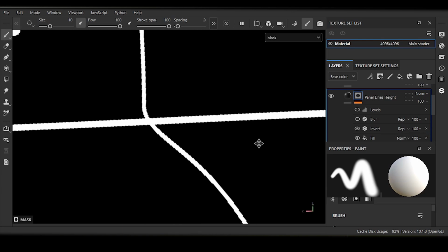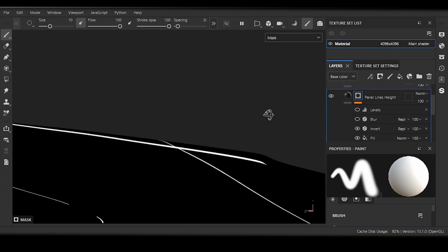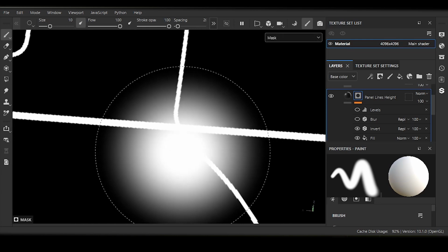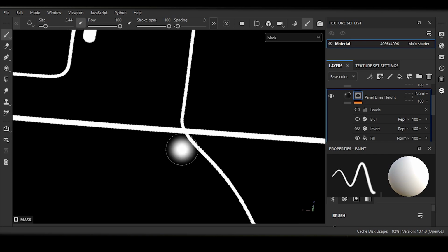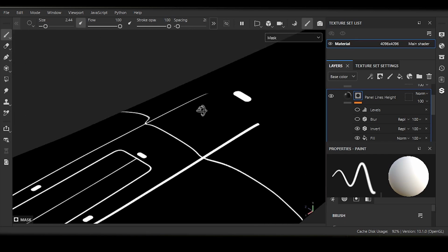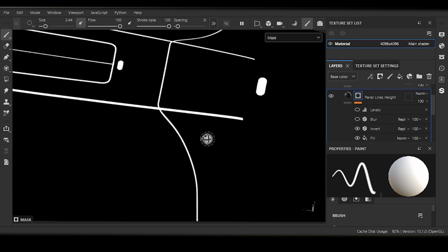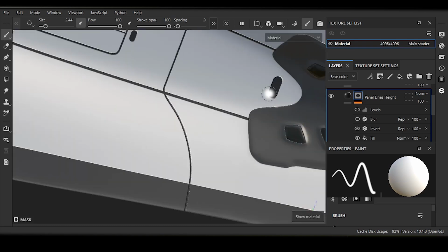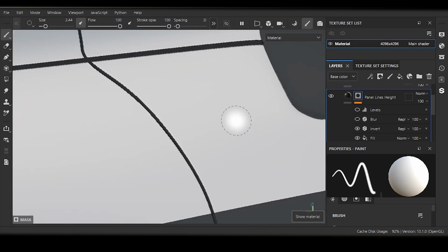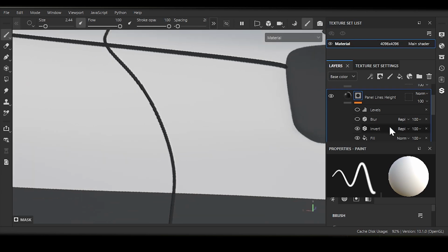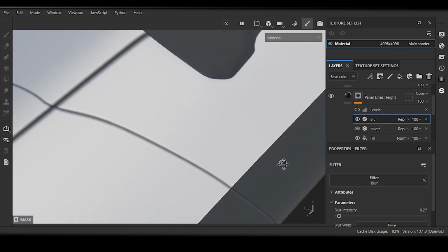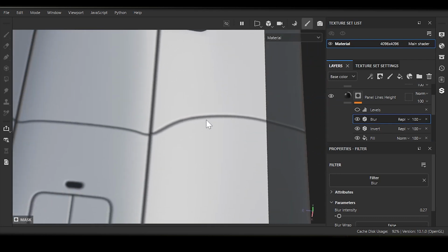You can see that the texture paint in Blender doesn't really have anti-aliasing. So you can't get the smoothest lines by painting the panel lines in Blender, but because I had the reference already in Blender, it was more accurate to paint those panel lines in Blender. But what you can do, if I go over to the actual material view so you can see this, is smooth those out with a little trick by first of all blurring the lines here, which does smooth it out, but it makes it a bit too blurry.